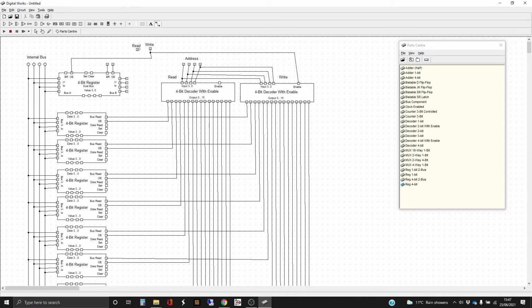And we want the opposite effect for the read command, which is that we want to take the contents of the memory location and put it into the data register, so the IO data register. So we're going to enable on this one, which then gives us output enable for the correct memory location. And so we need to bus read. Let's do a little bit of a jiggle.